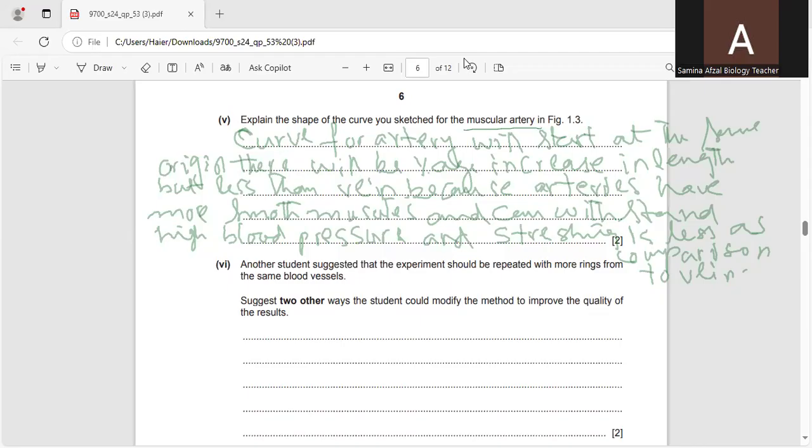In the previous question, I had also used the word force meter. So first of all, I would like to tell what a force meter is. The force meter is also known as a force gauge or dynamometer. This is the device used to measure the magnitude of a force. It works on the principle of elasticity, where an elastic component, usually a spring or a metal strip, is deformed when a force is applied. This amount of deformation is proportional to the force, and this relationship is used to determine the force magnitude. And the force meter is of two types. One is the manual, which is called the spring force meter, and the other is digital force meter. So both of them are used for this purpose.